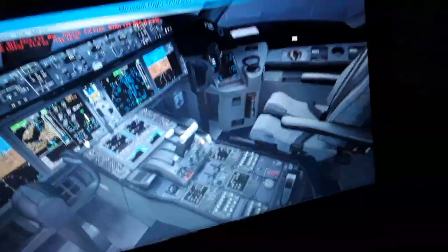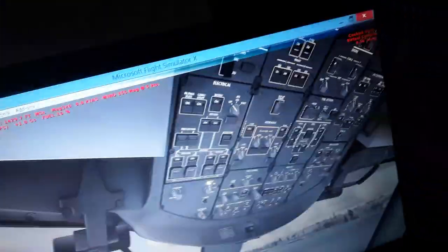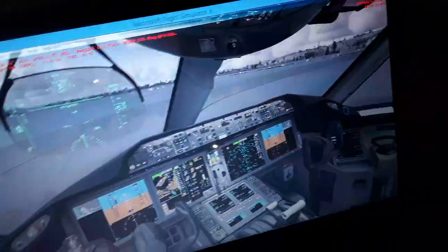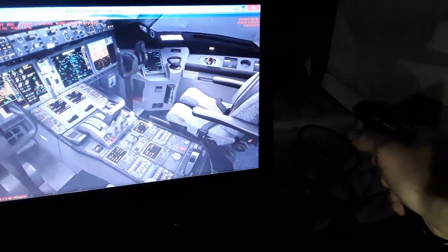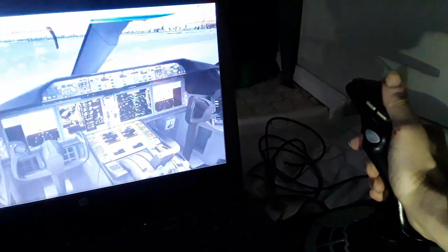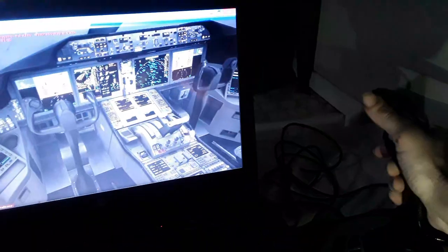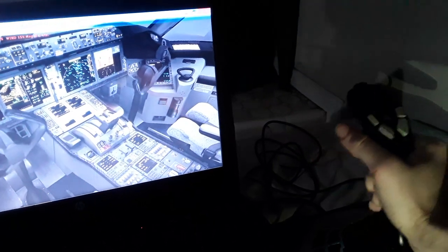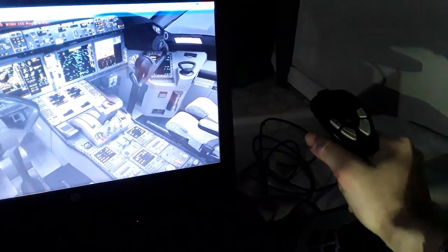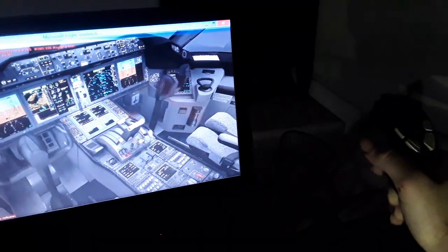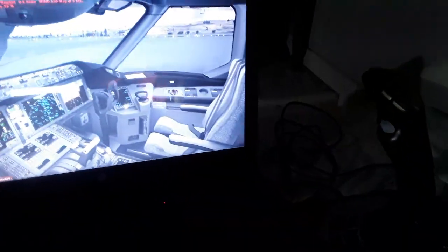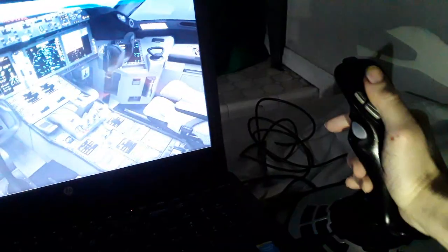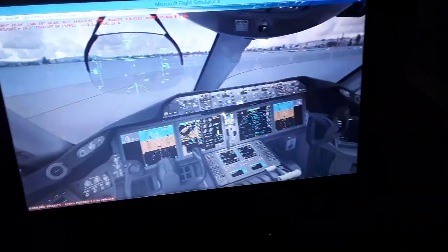From the direct, you have the normal, the alternate over here, and the direct control, like in the Airbus. So on this fly-by-wire aircraft, you move the side stick or the yoke. You give a control input to the flight control computers to move the flight control surfaces accordingly in flight, whatever you need to do to balance the aircraft, for instance, or change the direction. So maybe it's a little bit easier to fly in some conditions.